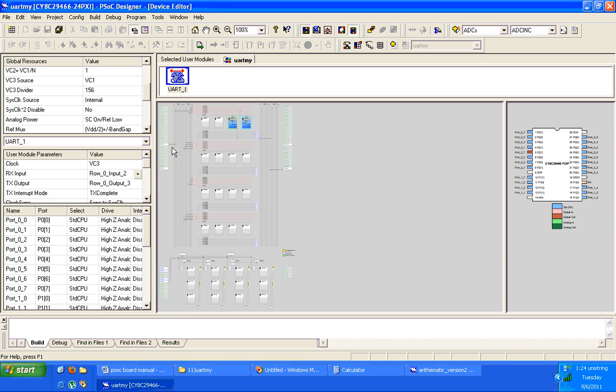Coming to the receiver, so the receiver part is over, 1.6. I am connecting 1.6 for the receiver, and the transmitter I am connecting to row 0 output 3, which is connected to port 2.7. After that we simply set all the user module parameters. Buffer size is 8 bit now, so 8, and here this is your choice, no need to fix the same. Give some parameters: 13, 32, 32, 32 bit, 32 bit, and disable none. The remaining options are given none.